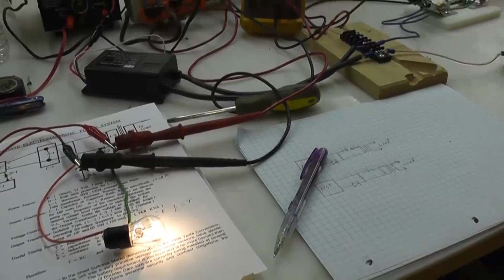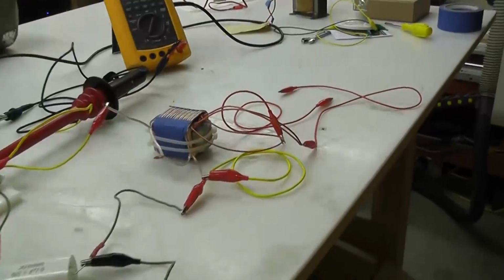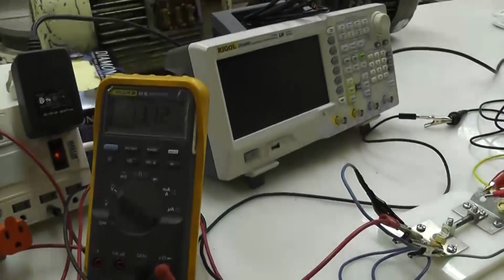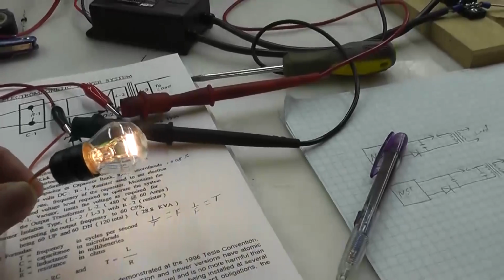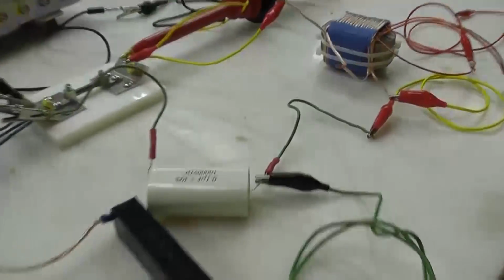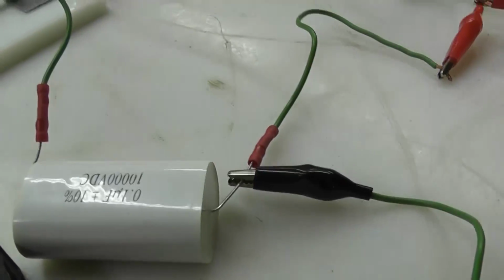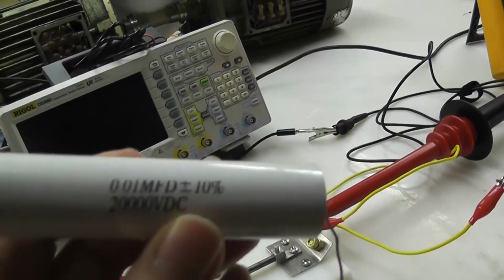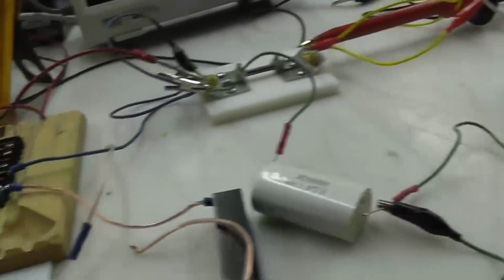And if I had my oscilloscope, I could measure the voltage on this while it was plugged into that transformer. I think what's happening is the frequency coming out of the end of that is just too much for this guy right here. So anyway, I'll set this back up and I'll show you what happens when we mess around with the earth ground, and we will change this capacitor, which is the 0.1 microfarad capacitor, to this capacitor, which is a 0.01 microfarad capacitor. Okay, so I'll set that up and be right back.